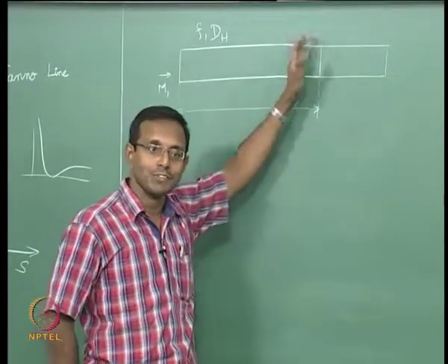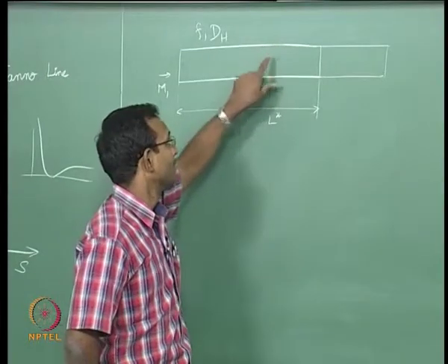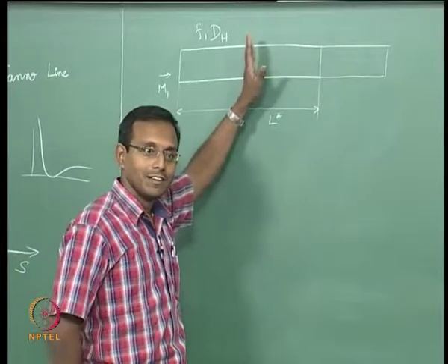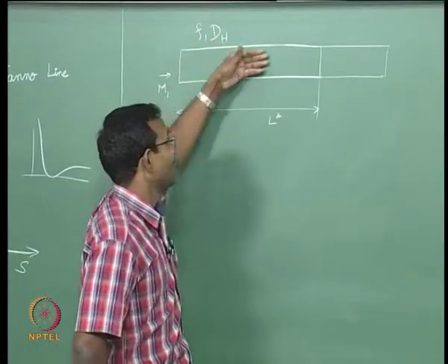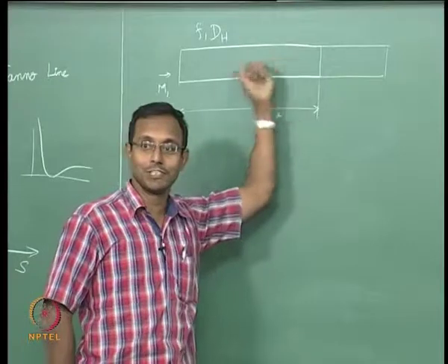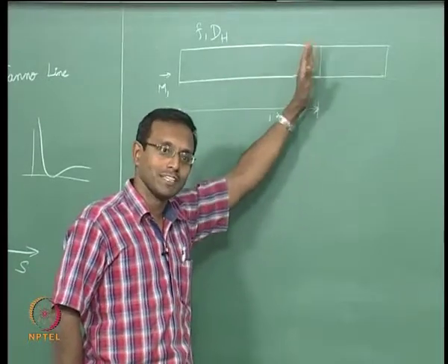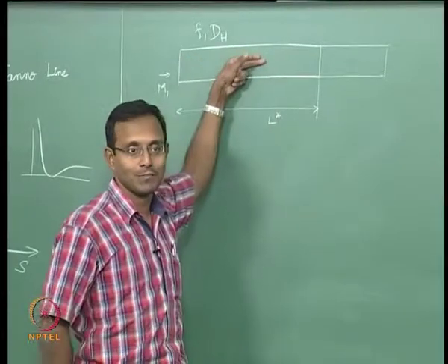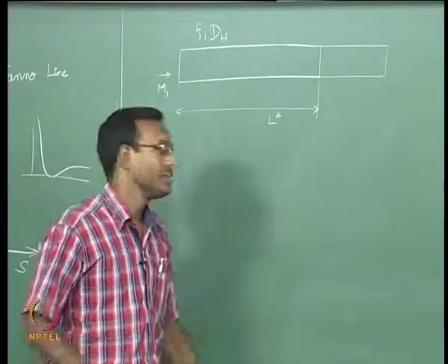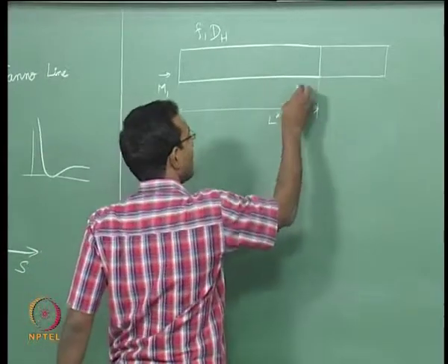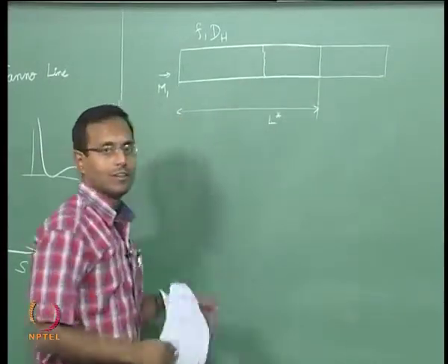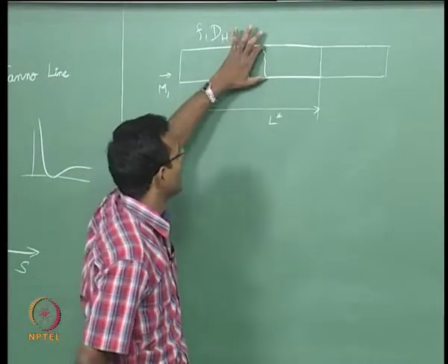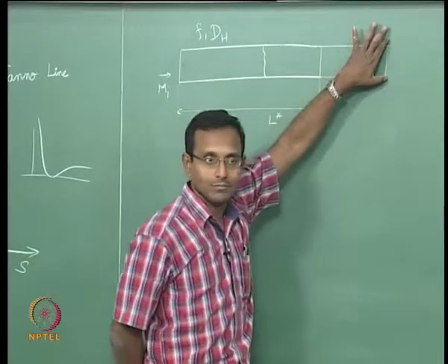When there is a bunch of compression waves going in, they will come together and form a shock, and as it goes in, it cannot keep going in, because at some point Mach number will be higher than the Mach number of this shock. It is a moving shock. It will go and reach a point where the moving shock's Mach number will be equal to the incoming flow Mach number, and it stays there. Okay. So then I will go to a point where there will be a shock here. After that it is again 1D shock, right? So it is going to be subsonic flow behind. Now I have subsonic solution from here all the way to the end.